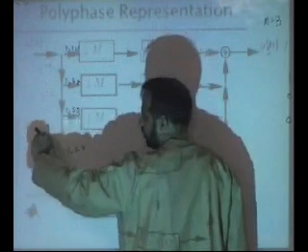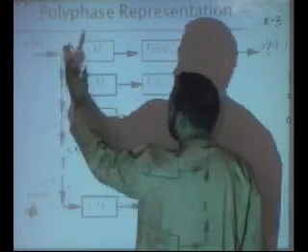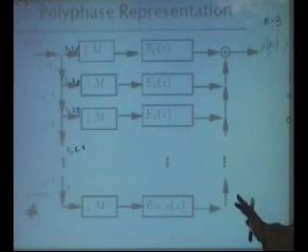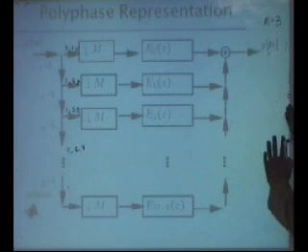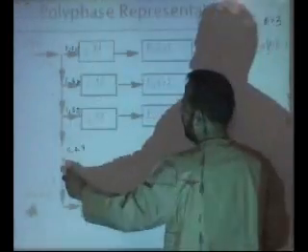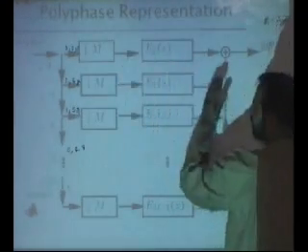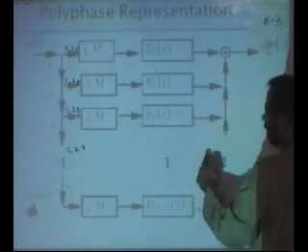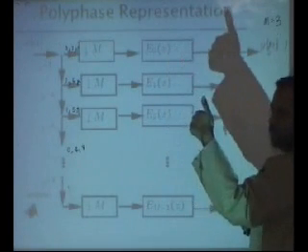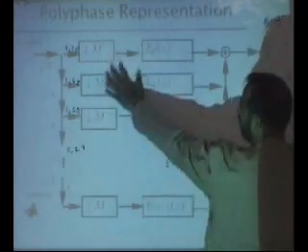It gives first sample here, second sample, third sample, fourth sample, and then you run this filter, which is 4 times slower clock rate, because first you distribute, then you compute, then you again distribute, then you compute, and every 4 samples you compute 1 sample at the output, because this is a filter. So you give 4 samples, you get 4 out, add them up together and produce 1. So for every 4 samples you produce 1 sample. This is decimation, and the filtering is automatically happening here.